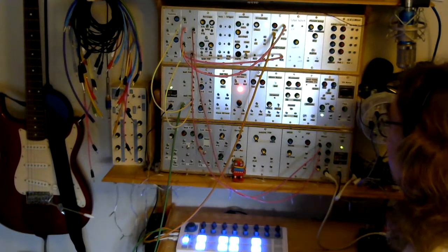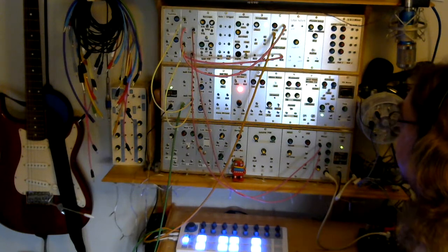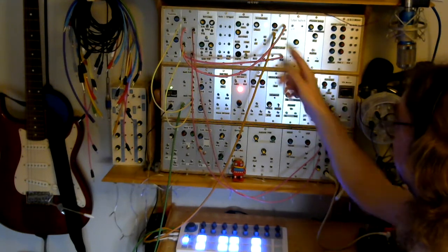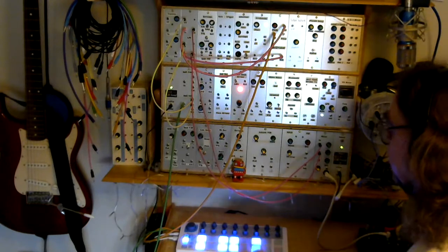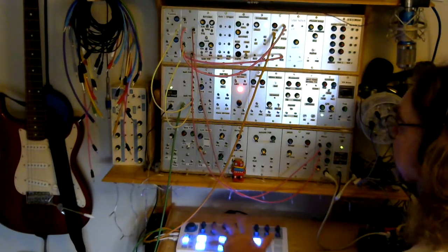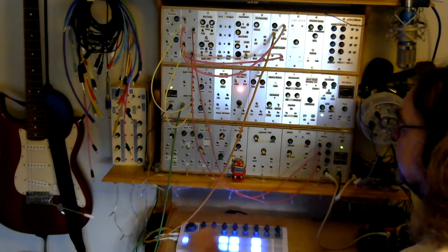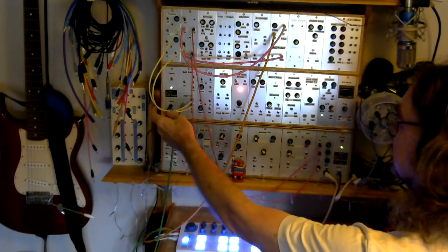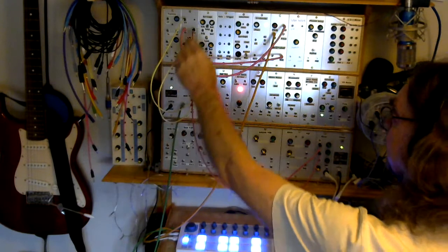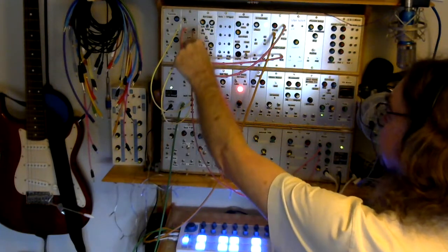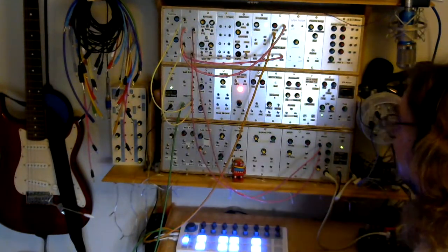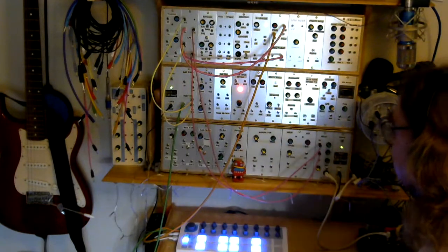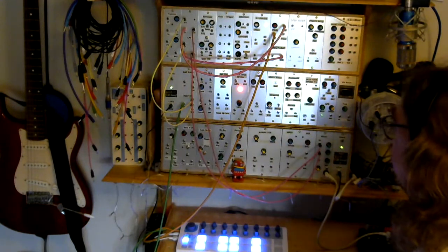The pitch of the Octivator's oscillator is fed a CV signal from a simple sequence I've set up on the beat step. The gate from the beat step goes into my gate buffer, which allows me to split the signal and use it to drive both CVs on the low pass gates, so everything is synced and in time with each other.